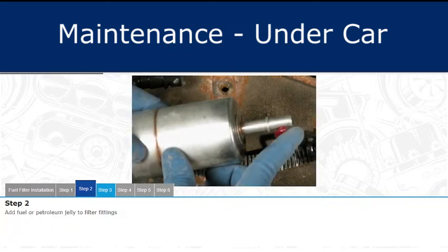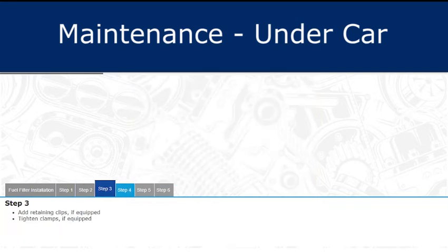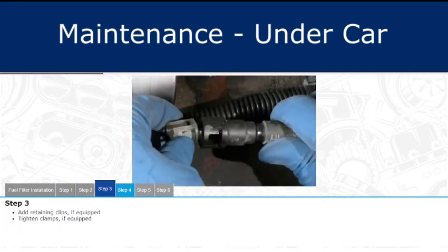Add a little fuel or petroleum jelly on both filter fittings. This helps the hoses to slide over them easily. Add the retaining clips, if equipped, so that the hoses do not slide off. If the vehicle uses clamps, they should be tightened at this time.